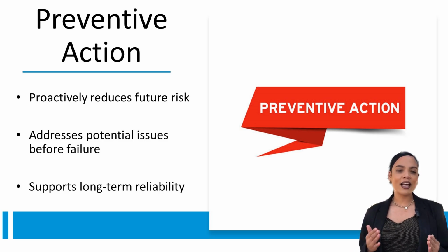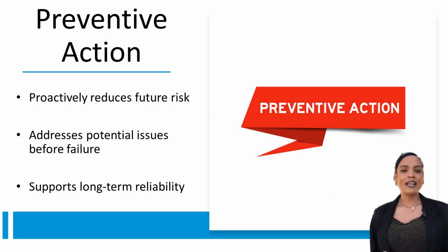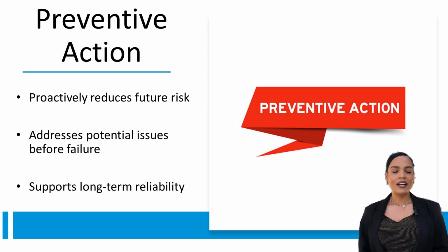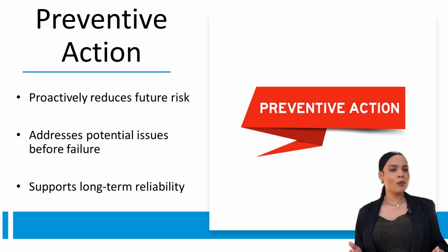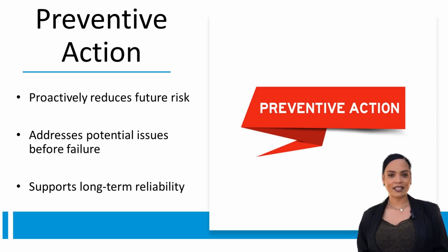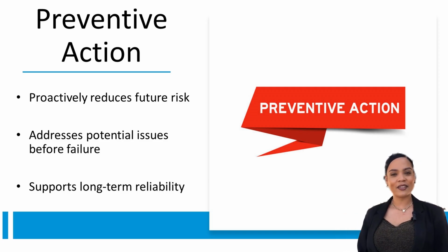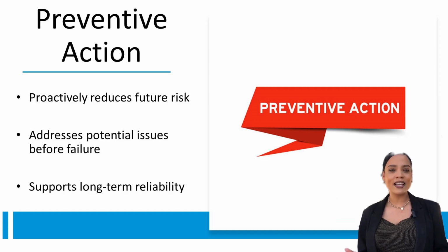2. Identifying risks. We can identify risks based on trends in data, small increases in defects or downtime. Near misses. Events that almost caused harm or failure. Audit findings. Weaknesses in compliance or controls. FMEA results. Failure modes with high risk ratings. Operator feedback. Concerns and suggestions from people doing the work daily.